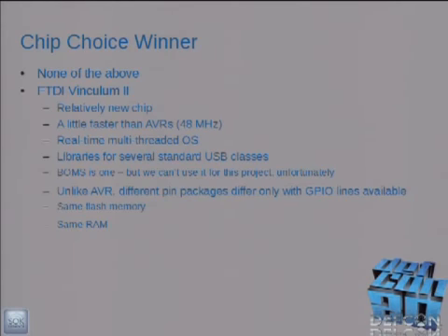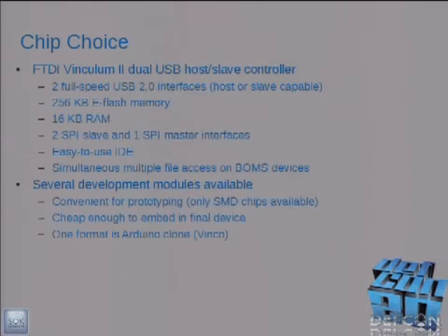A couple years ago, FTDI, the people that make those little USB interface chips, came up with a microcontroller of their own. Maybe they got tired of just making the interface chips. It's a little faster, 48 megahertz. And unlike the Arduinos, it has sort of a proper real-time operating system. It's got threads and semaphores and cool stuff like that. And more importantly, USB classes.